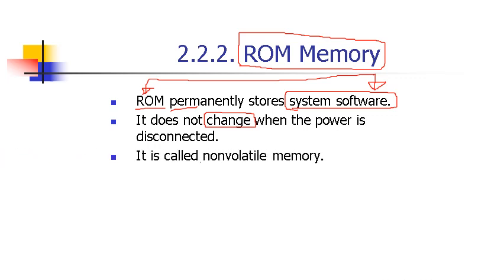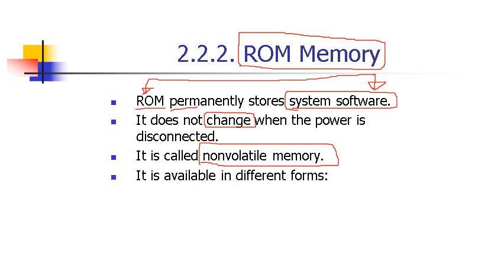And it is also called non-volatile memory. Again, the term non-volatile memory indicates that the data is retained inside your memory. It doesn't go away. And these devices are available in forms of PROM, programmable ROM, devices that can be programmed. But again, after being programmed, you can only read the data from it, and you don't lose your data if you turn off the power.